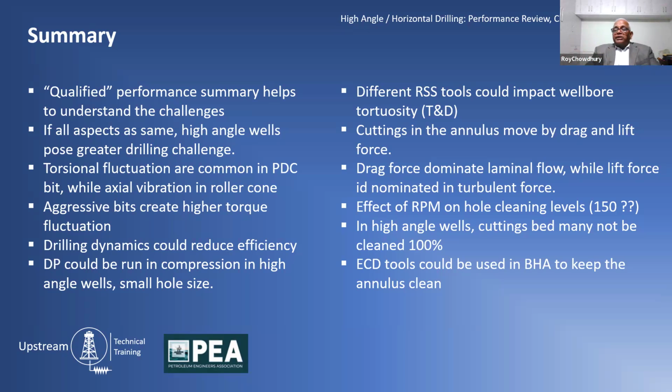Because if you look at the cosine curve, you note that cosine varies, and after 45 degrees, the benefit doesn't help anymore, because you are working against yourself, increasing the torque and drag. So this is my personal experience. I do not put the heavyweights above 45 degrees.